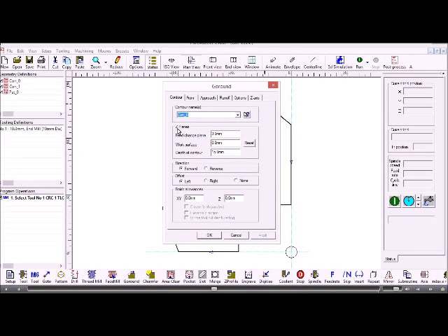Under Z planes, this is the information that's previously been set. We set the work surface to 0 and we set the depth of the contour to 15 when we created the contours. But if I want to change my mind, I can simply put in a different value here. For machining in the forward or reverse direction, and then the offset is applied after the direction is set. So if we wanted to go clockwise around there, that's the forward direction, and the offset is to the left.